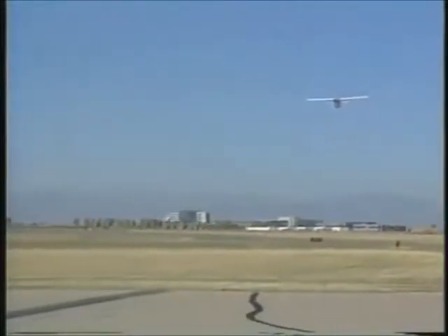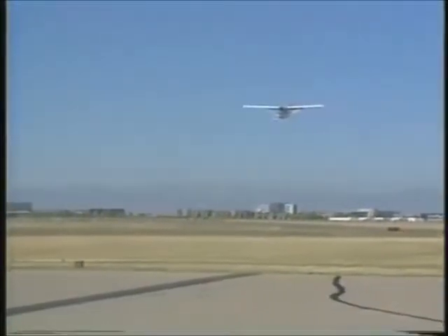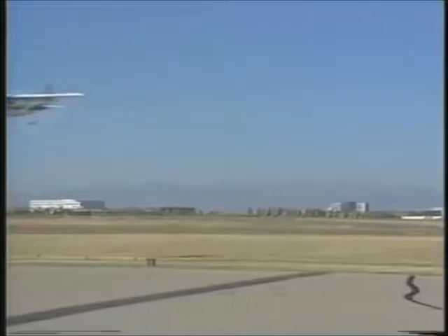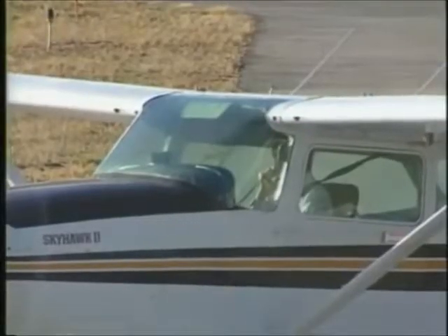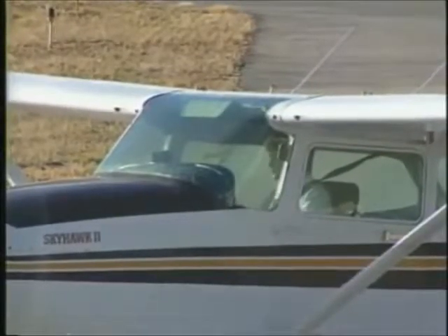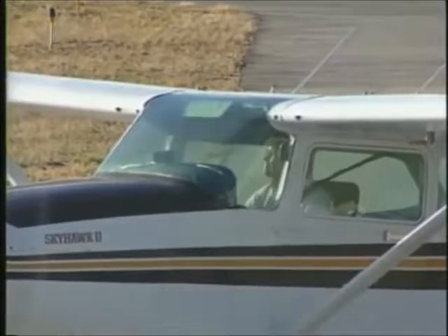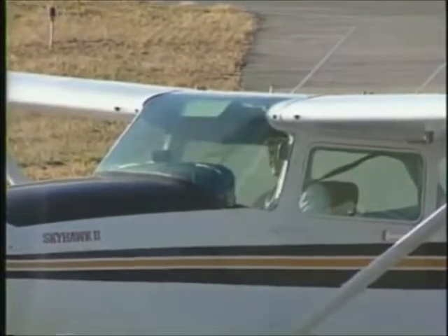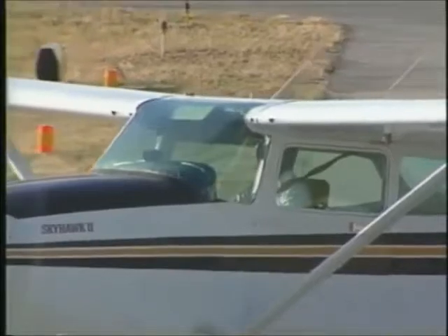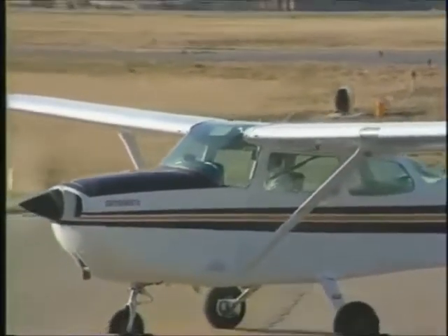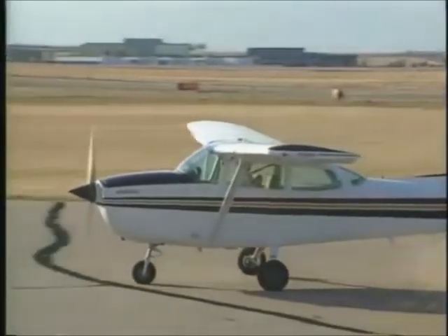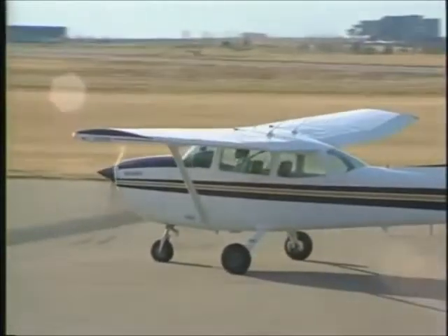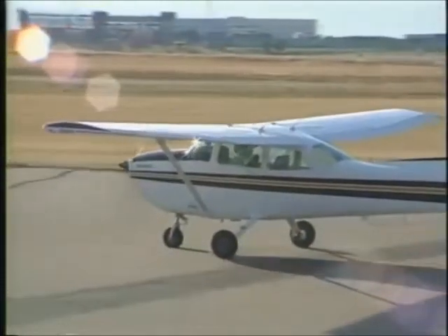If other airplanes are in the process of landing, the controller will advise you to hold short. This means that you are not authorized to taxi onto the runway and should remain at the holding line. When the final approach path is clear, the tower might ask you to taxi into position and hold. This authorizes you to taxi onto the runway and line up on the center line for takeoff.